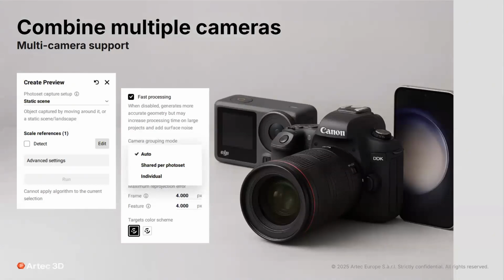One more feature that we've added with Artec Studio 20 is the ability to combine multiple cameras. Here you will see under the advanced settings for the Create Preview tool that now we have a camera grouping mode option, which is responsible exactly for that. You're presented with three options: auto, shared per photo set, and individual. The auto mode is best suitable for when you are filming with just a single camera, which, to be honest, is the most common workflow. So it is set by default.